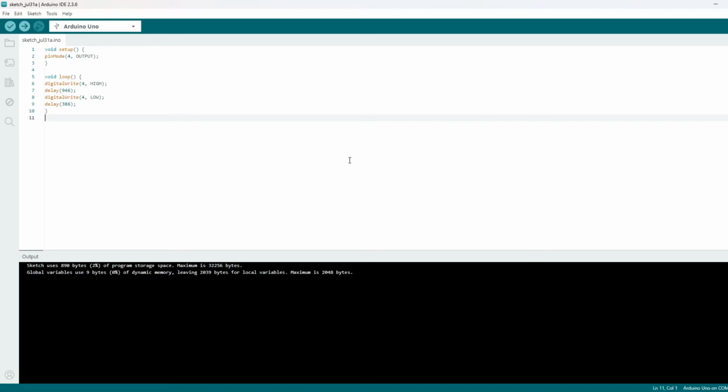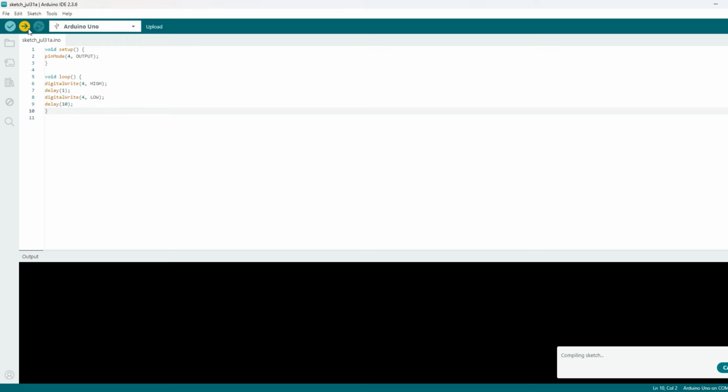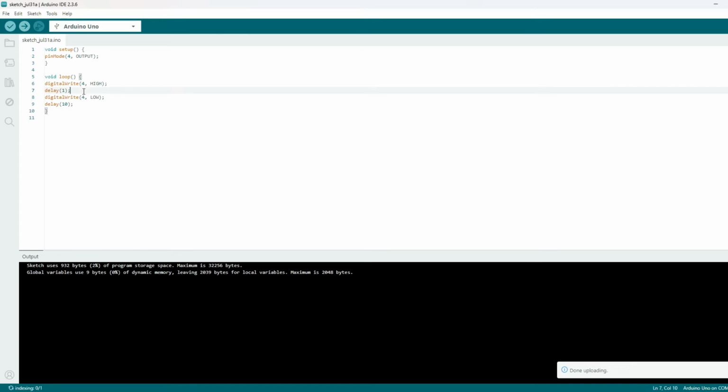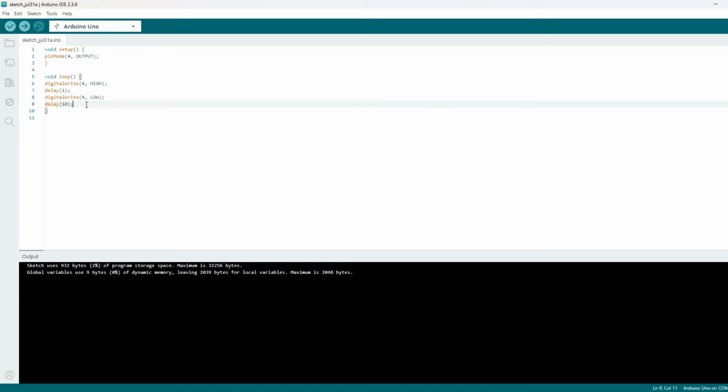But now let's do a little experiment. Let's set this to 1 millisecond and this to say 10 milliseconds. So it's going to be on for a tiny amount of time and off for also a tiny amount of time, although it's going to be off 10 times longer than it's on. But now let's upload this, and it's actually going to be turning on and off so quickly that you won't be able to see it. So look at your LED now and tell me what you see.